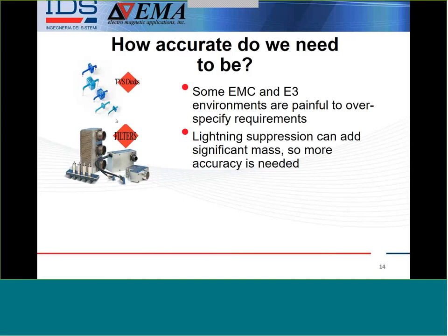It's not easy. And heaven forbid, everything today is commercial off the shelf. You're going to have to certify a metal aircraft, or a composite aircraft, with equipment that was made for metal aircraft. So you're going to have to put in a filter box, and that box itself is going to add 10 pounds of mass. So that's not necessarily an ideal approach either.